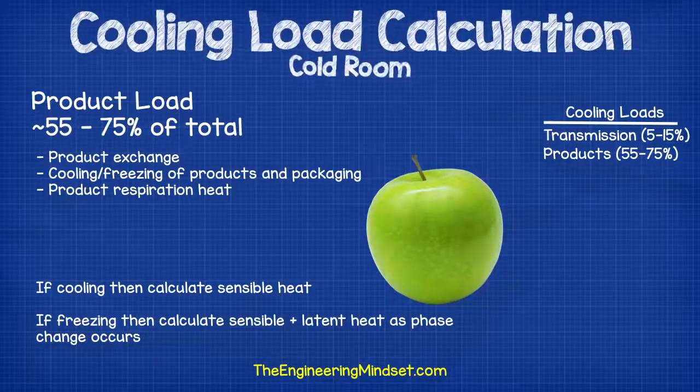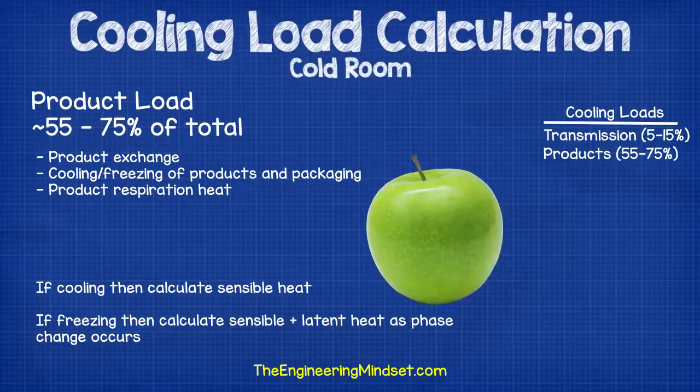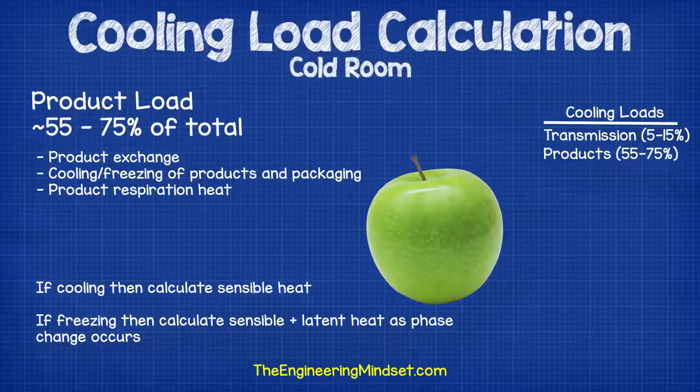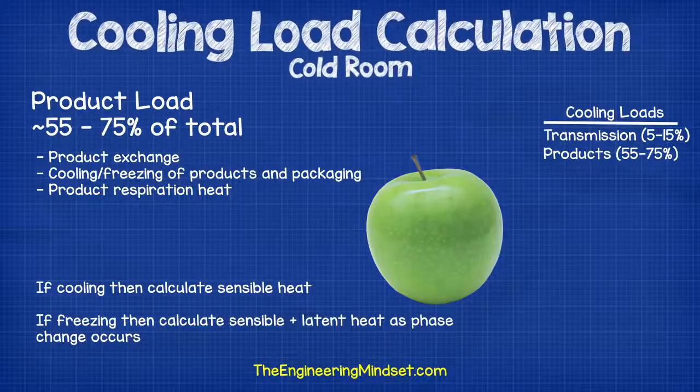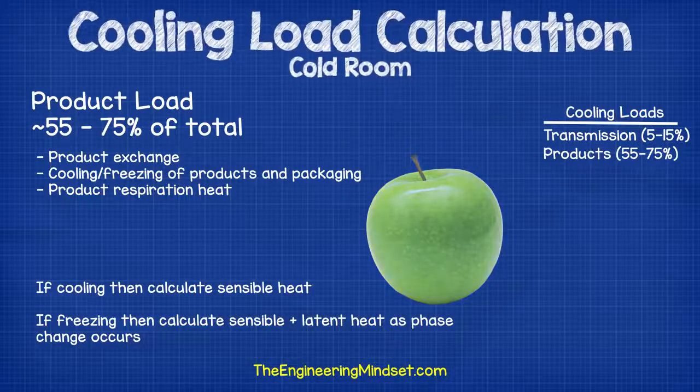You also need to account for the packaging, as this will inherently be cooled also. Lastly, if you're cooling fruit and vegetables, then these products are alive and they will generate some heat, so you need to account for the removal of this also.